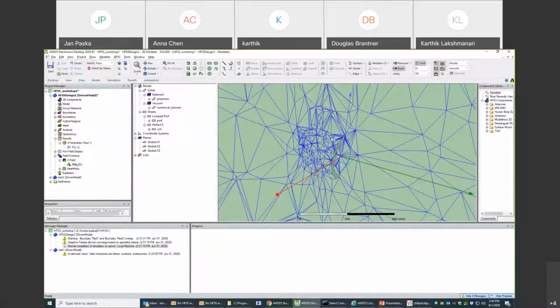I could choose a 4 times finer mesh, but the computation time will be like 100 times longer because it doesn't scale linearly. So it chooses an initial mesh that's not too fine to have a good approximation for the solution. And then in the following steps, it will discretize the space finer.